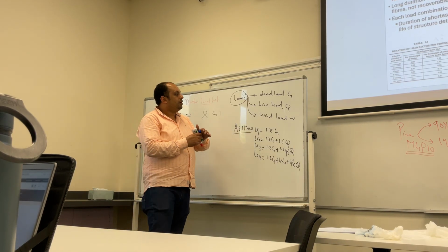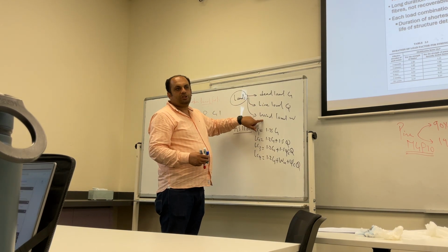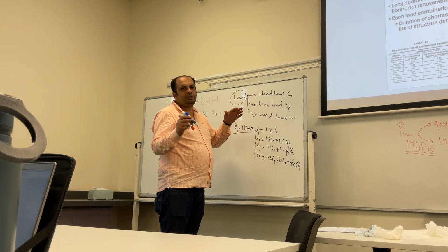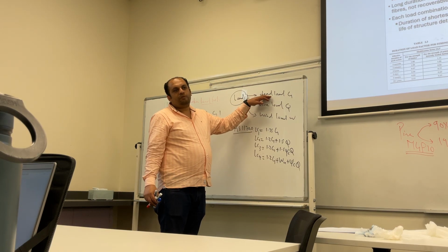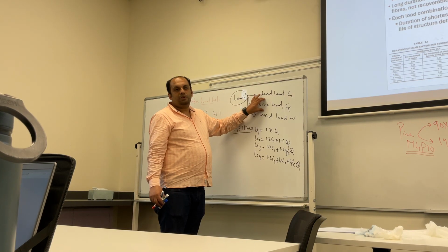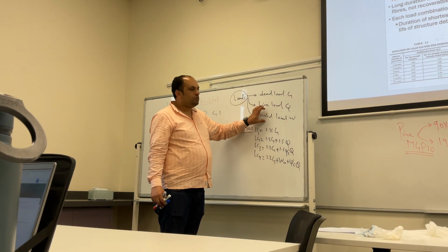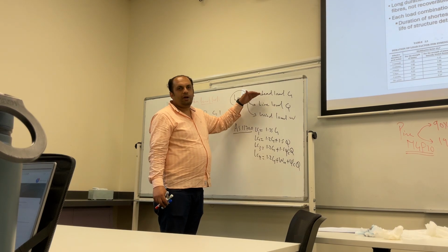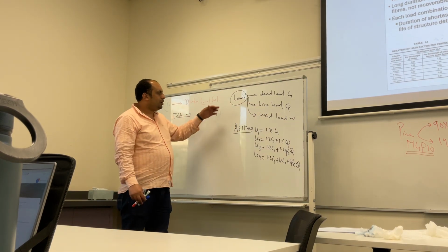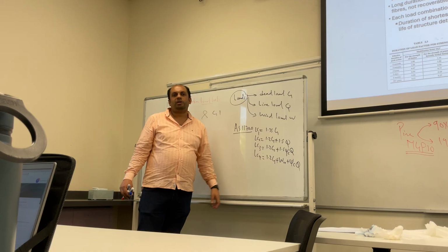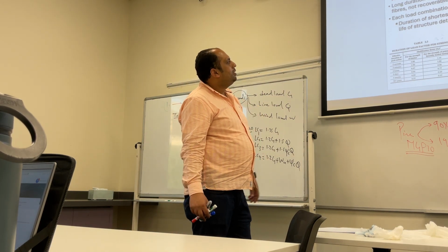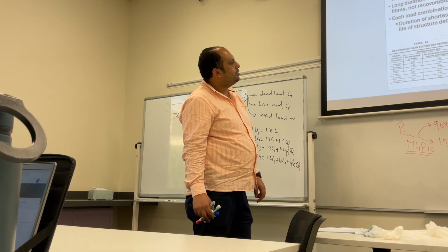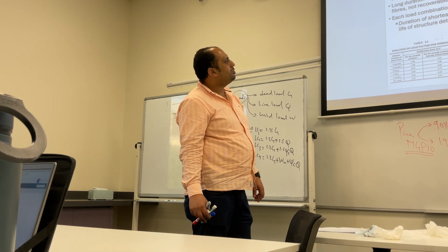These loads, are they applied to the structure for the same duration or different? The dead load will be on the structure for the whole time, right? So it's longer duration. Live load, it can be for shorter duration. Wind load also for shorter duration. So when we are applying K1, we need to consider each load alone and each load combination alone. So each load combination taken separately to find K1, the duration of the shortest component of each combination over the life of the structure determines K1.